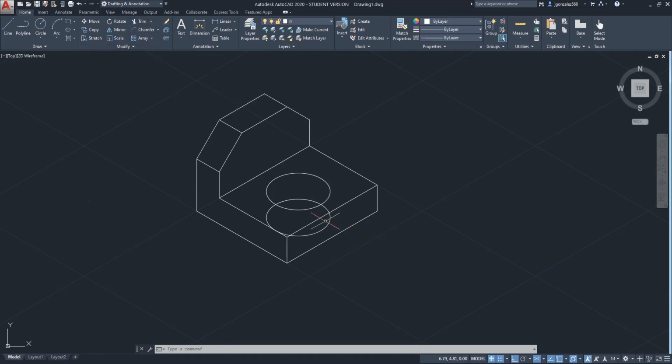So what I want you to do is trim everything of the lower circle except the inner piece. So choose trim. Select the two circles, press enter, and delete everything outside. So give it that depth perspective. It looks like a hole now, which is kind of cool.